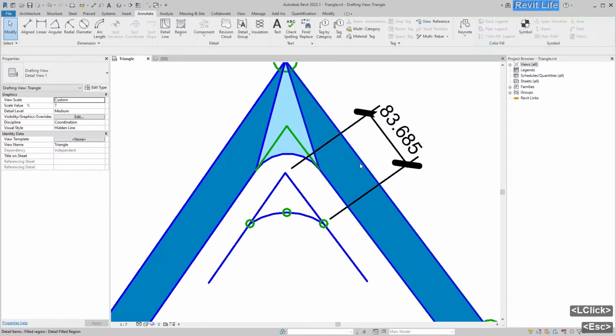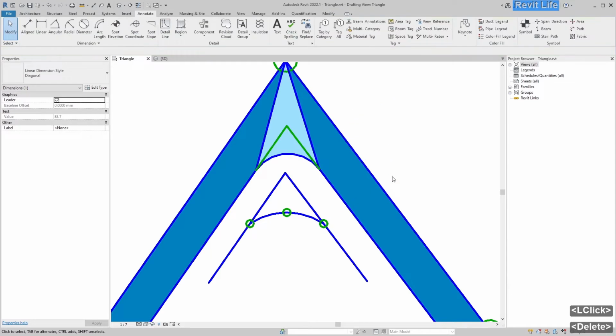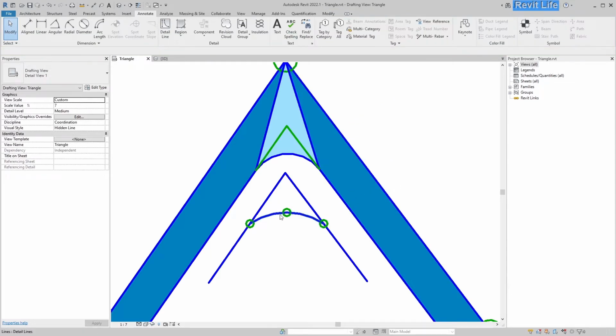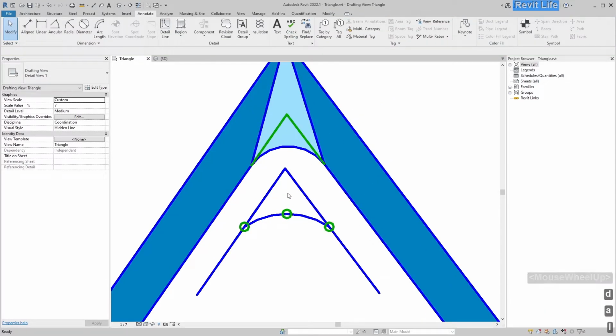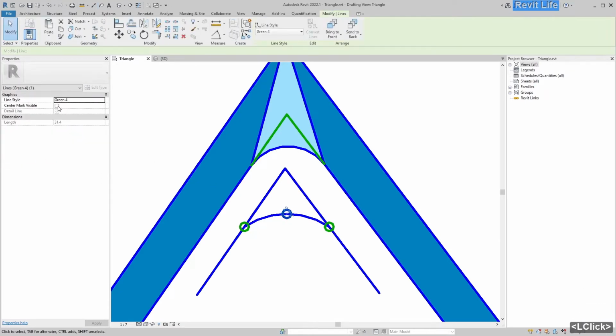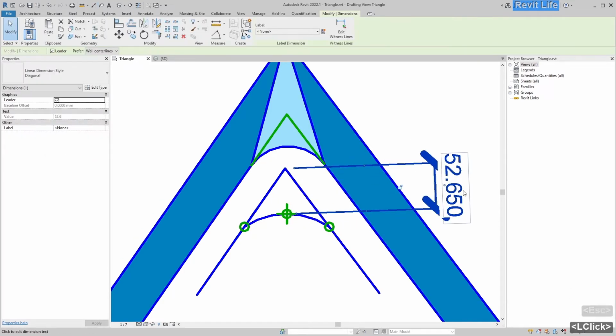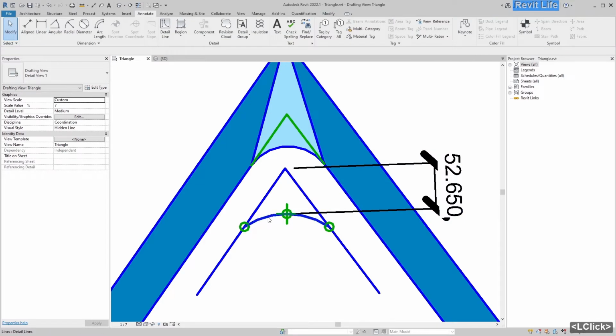We call them the fillet length, and we can use that number to calculate the radius needed for the arc to be tangent to those 2 lines. This length from the middle of the arc to the corner is not necessary. We cannot use this number to calculate the radius for the arc.